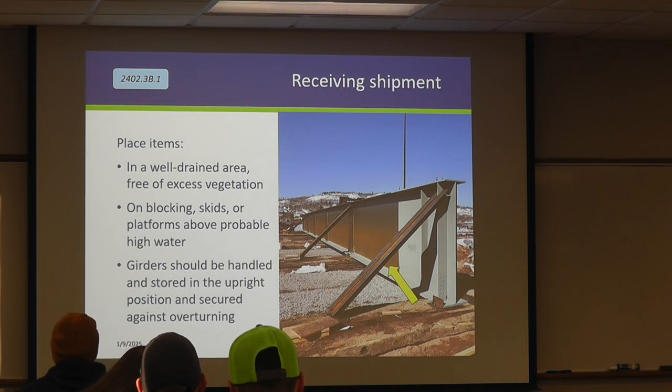And then girders do need to be stored upright. So you can see that can present a challenge. This contractor provided some of these angles to provide stability because we want to keep a safe environment too, right?